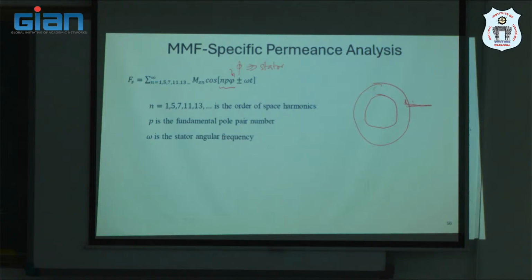I will also introduce an expression where phi dash is the angular measure in the rotor reference frame, and omega r is the frequency associated with rotational motion on the rotor side. Okay. So what is omega r? Slip is defined, in an induction motor, as omega minus omega r over omega. So omega r is 1 minus slip times omega.